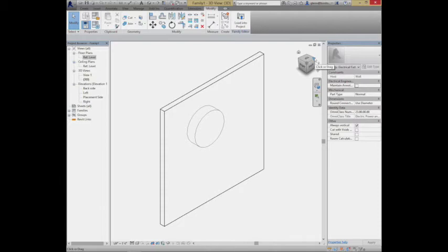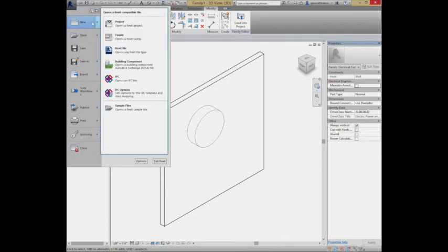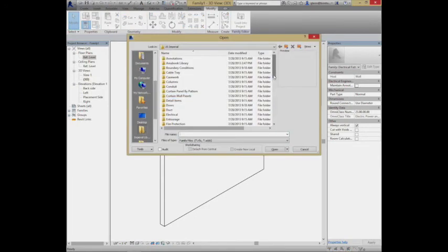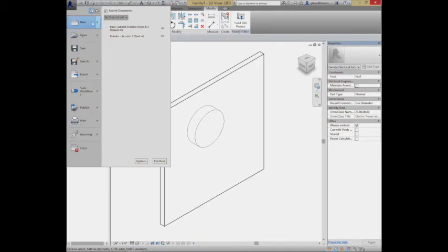Now if I bring it into my project, it'll stick that onto any wall that I choose. So for wall-based hosted things, it's really just getting a template of one. You might even recognize that doors and windows are examples of things that are hosted that way. So for example, if I say new family, let me see if I have a door.